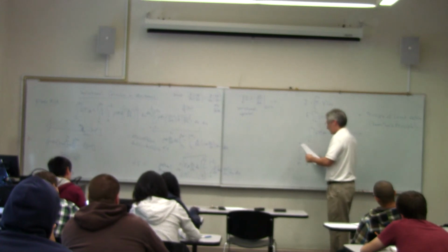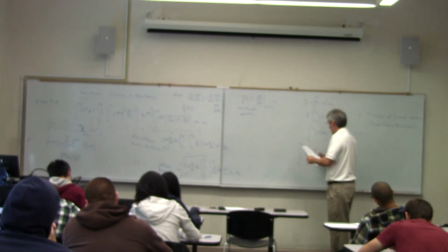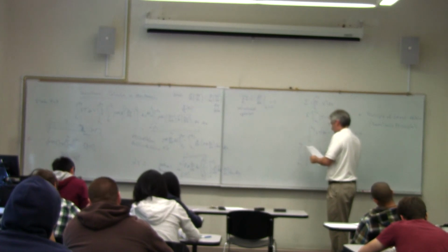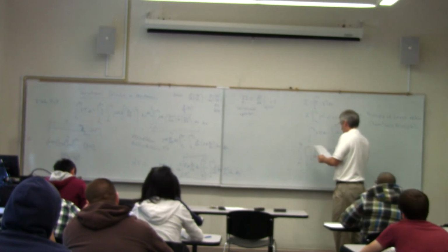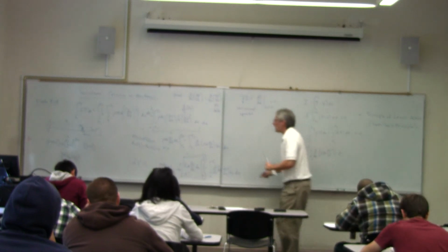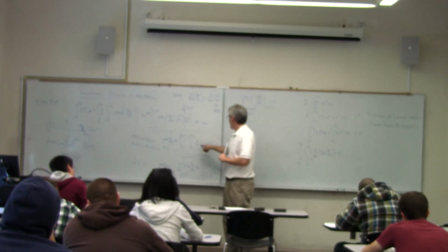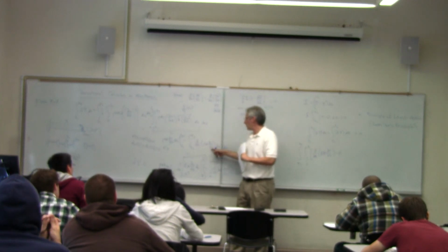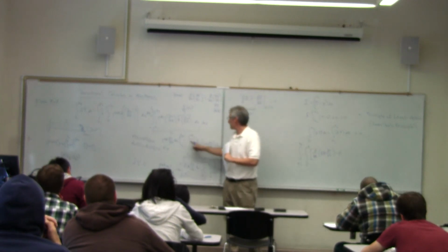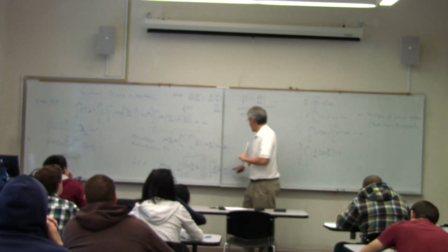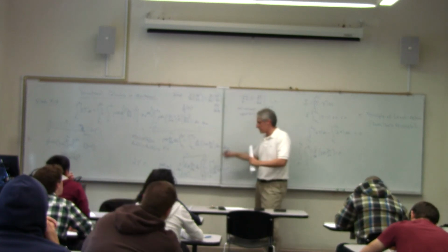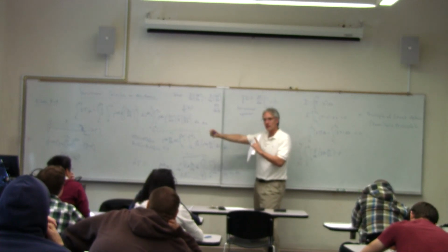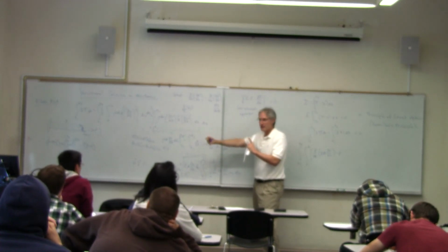And then this is going to be partial with respect to x, EA partial u partial x minus, now by the way, rho and a don't depend on time, so we can bring this all the way through, whereas for the other one, it could be that the cross-sectional area or the modulus of elasticity might change as you go along the rod, if it's not a uniform rod.